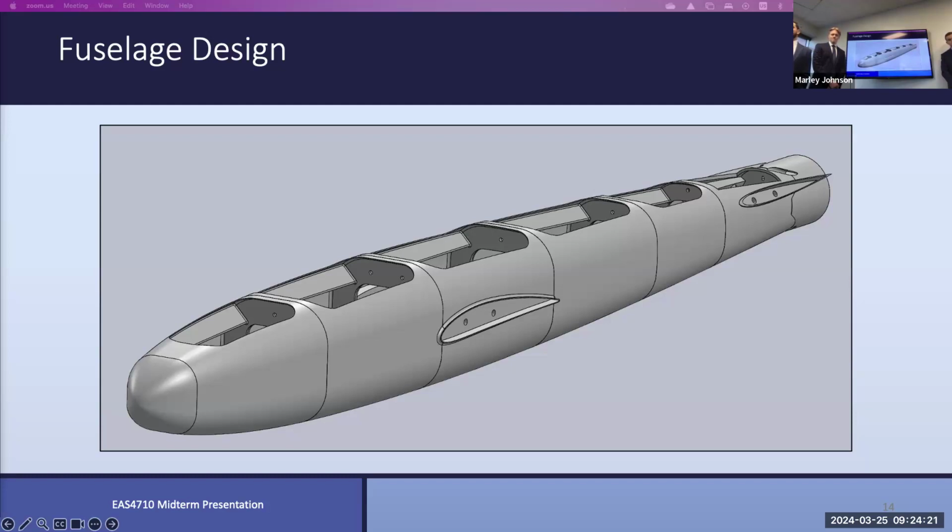When you talk about the ESC, you mentioned that you need it because it helps with thrust reversal. Why do you need that? Well, we had a target, and our goal was to do a survey of some application flows. When you're landing, we don't really have good braking and we're targeting 8 to 10 pounds. We want to be able to slow it down once it lands, so it was a feature we wanted to incorporate.